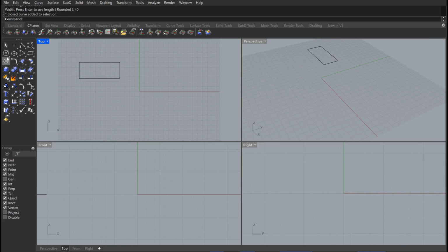And if I wanted to make a polygon, then I'd press this command, or I type polygon. Polygons have many sides, as we know, so if I want to define how many sides my polygon will have, I'll press N. I type N and press enter, and now it's asking me to define how many sides our polygon is going to have. Let's make this an octagon. Let's make it 8 sides.